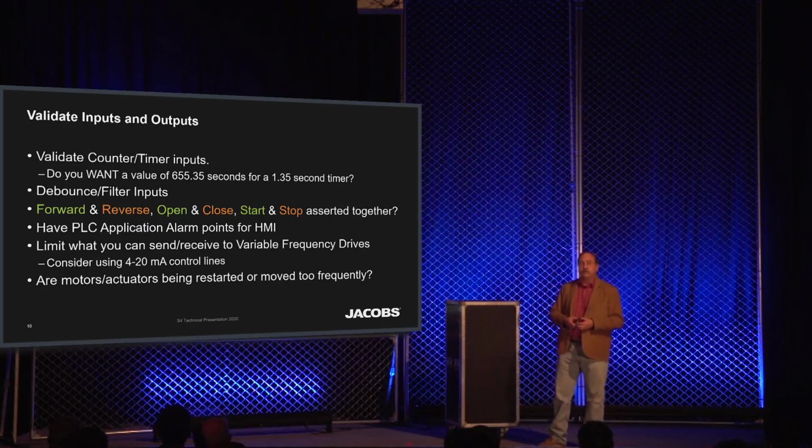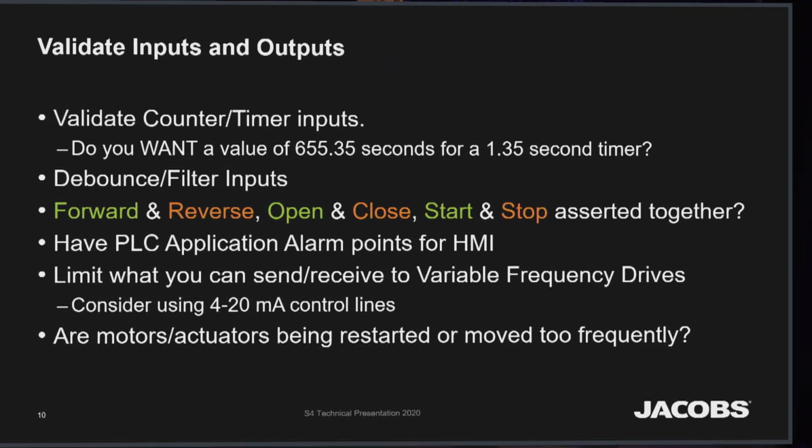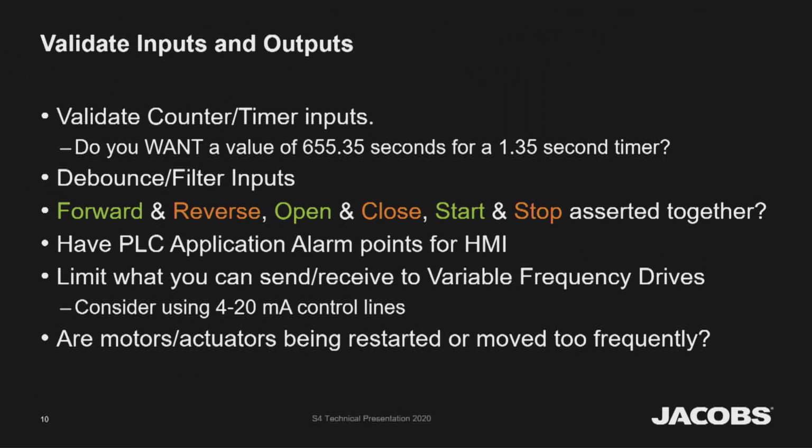Everybody just says, well, the HMI won't do this to me. Why not? It might not even be the HMI on your network. Don't trust it. Other things you want to do, modern PLC cycle times are fast. You might want to look at possibly debouncing inputs. A lot of I/O cards give you that opportunity, but if the I/O card doesn't do it, you can do it within the PLC.